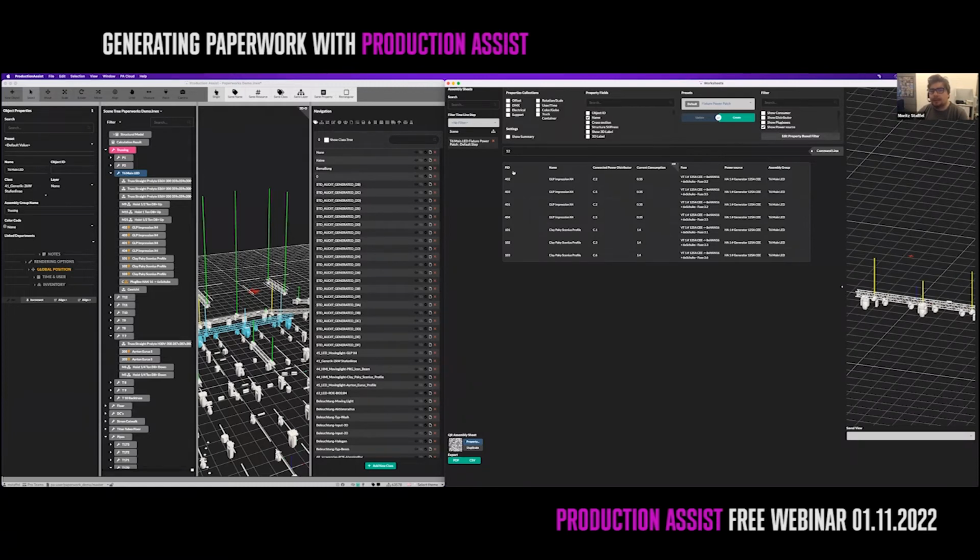So now I see in here, I have the fixture IDs from here. So I have 4 GLP Impression and 3 Clay Paky Sharpy Profiles. And I see how they are plugged into the specific plug box in here. I can sort by the plug box, for example, and then I see what is plugged into which. So the 101 is plugged into the port C1. The 402 is plugged into the port C2, and so on.